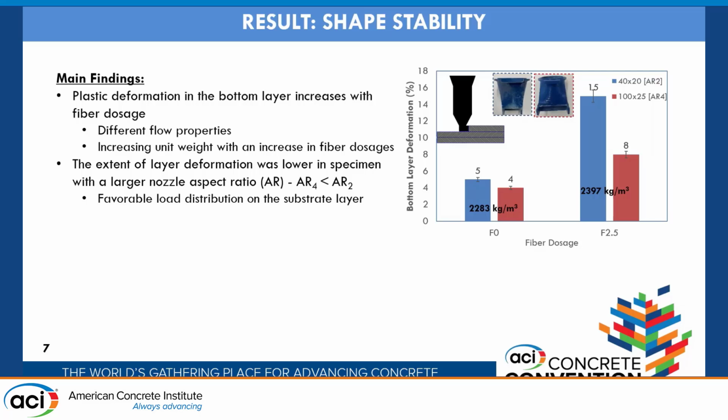And also we showed the effect of the aspect ratio of the printing nozzle as well. Our results show that generally printing with a higher aspect ratio led to lower plastic deformation.